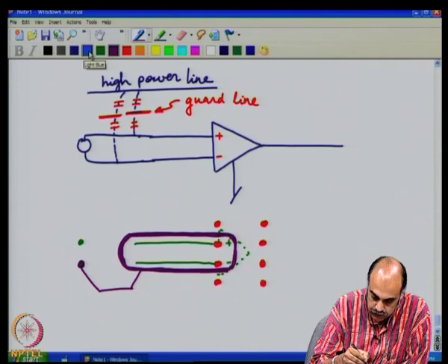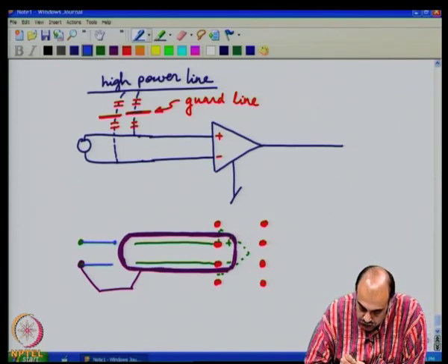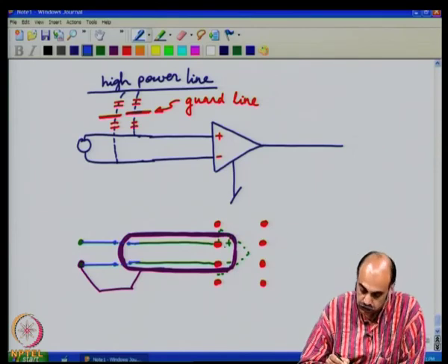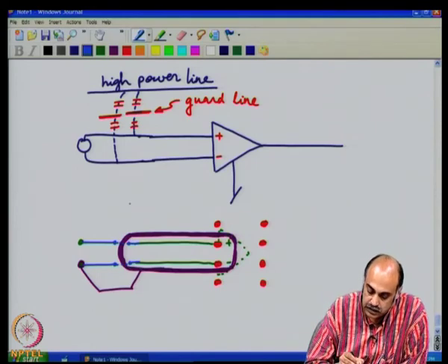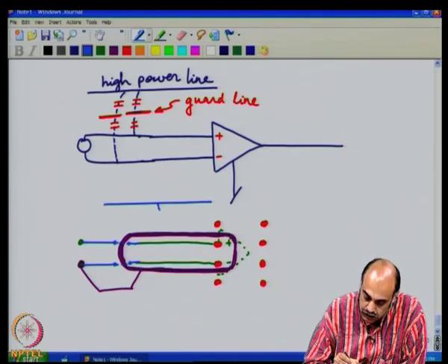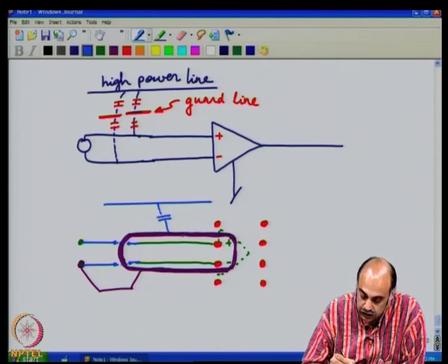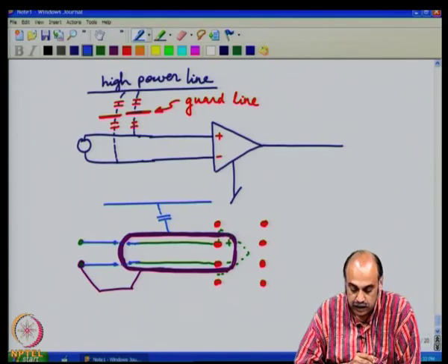And then from here onwards you could take in these wires, and probably through the other layer you can make the connection to the inner line. So, now you see these lines are guarded from any external line which has capacitive coupling to the guard, but not direct coupling to the two lines of the differential amplifier.